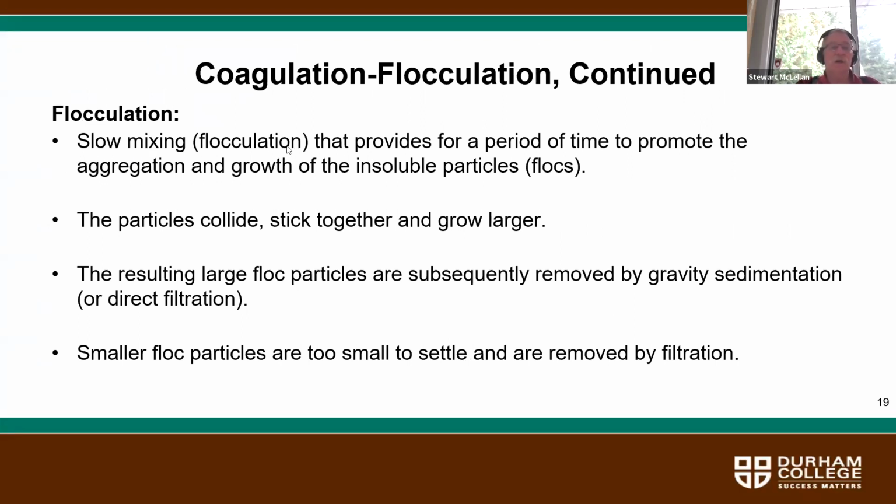Flocculation, slow mixing, provides a period of time to promote the aggregation and growth of the insoluble particles, which is commonly called flocs. You can see at the start here it says slow mixing. I don't know if you guys have done much wastewater treatment in any of your other courses, but when you're undertaking flocculation, you need to undertake it using slow mixing.